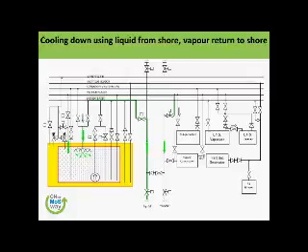So we will suck the vapor and give it to shore. But if the pressure in my tanks is getting high because I'm generating too much vapor and shore is giving me back pressure for receiving my vapor, I may have to take it to my compressor and push it out with force.